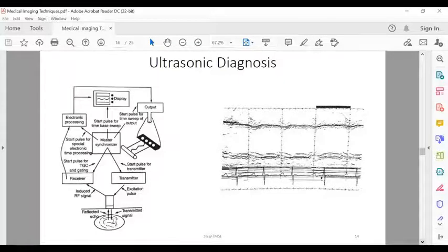Now, the ultrasonograph is used for imaging of the organ from several positions and helps in visualization of all four chambers and all four valves of the heart, and also the arteries and the veins. The systems for ultrasonic applications include a generator for the electrical signal, a transducer, necessary amplifier, and several electronic processing circuits and the display devices.